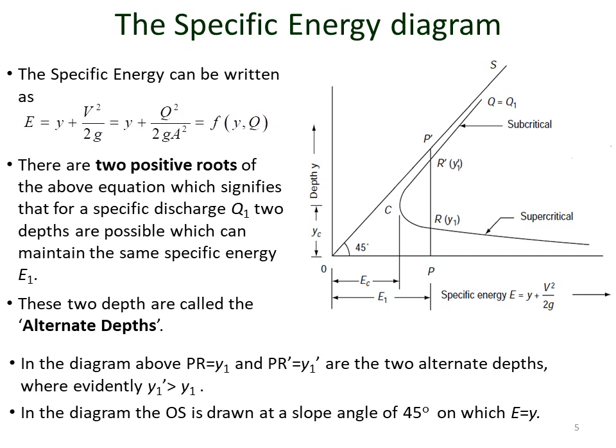So in this cubic parabola, you can find that there are two positive roots. It's a cubic parabola, so there are three roots, but two of those roots are positive. So two of those roots are going to represent two flow depths in the context of open channel flow. Of course, the figure on the right-hand side is the specific energy diagram, the cubic parabola, which is